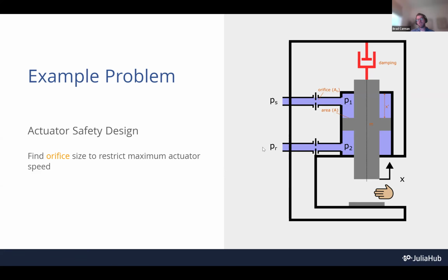So we're not going to include all of that in the system. The problem that we're going to try to solve is exactly what happens when that system fails. If you have a valve and a controller, and maybe one of the wires gets disconnected, for example, the controller is no longer live and you have an open loop.